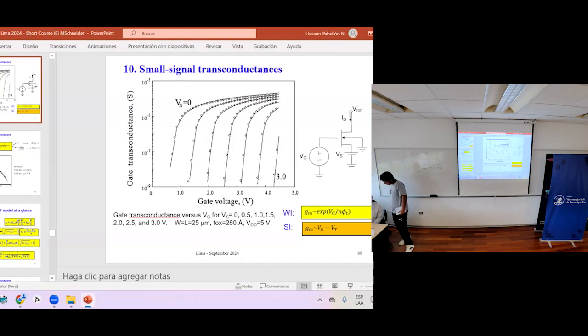then here, thermal, isothermal curves of temperatures. So here is, let's put something. Then you would have a temperature gradient from here. Then what do you do? Generally, instead of putting one transistor here and another there, you split the transistor. Say M1.